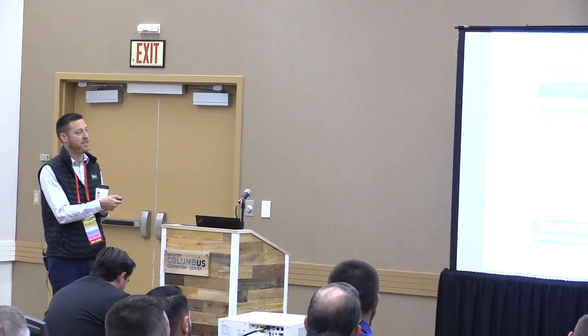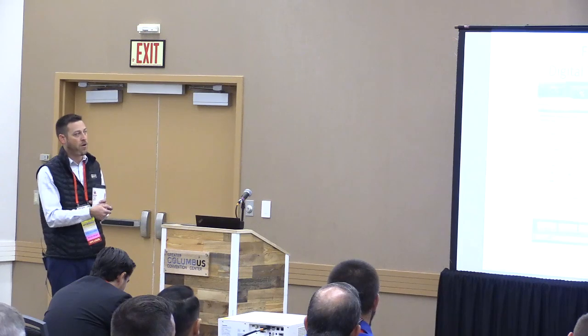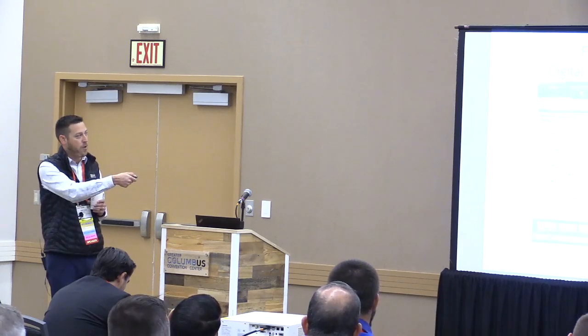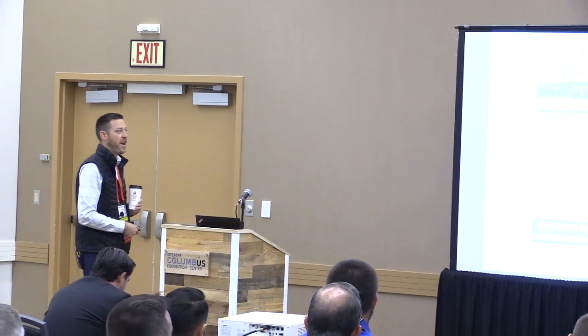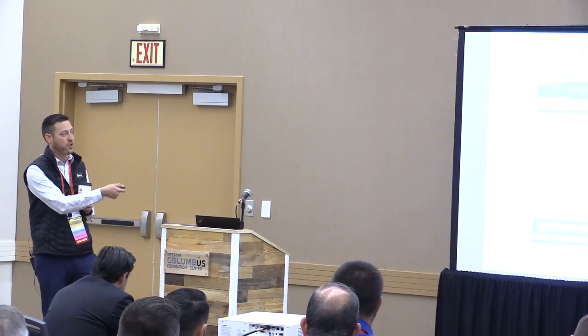The last thing I'll touch on is a lot of times when we have these digital power control units, we also get this where you can change the output during ramp. Now, are there business cases for having anything other than 100% during ramp? Yes, there might be. Let's say you've got really light, thin parts with high surface area, and they're going to come into soak very quickly, and you want them to come in somewhat uniform with temperature uniformity. Then you might actually tweak these.